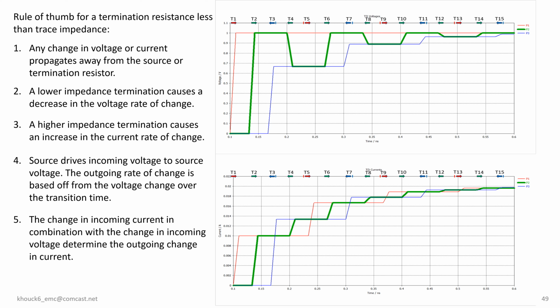Lastly, the blue line represents measurements taken at the termination resistor, which provide crucial data regarding signal termination and any reflection effects that may occur. At T1, Rule 1 is applicable as the propagation of the changing field wave is instigated by the drive. Furthermore, the current is contingent upon the impedance of the trace. At T2, the changing field waves traverse the midpoint.